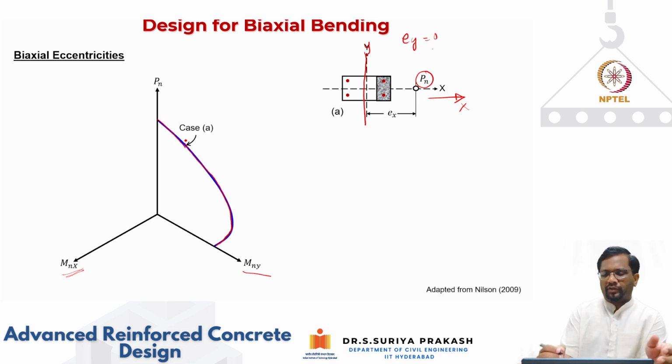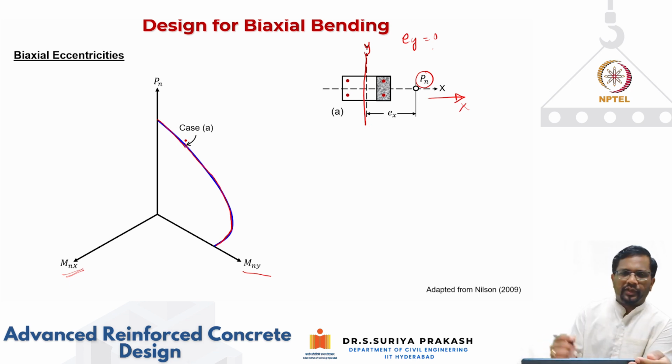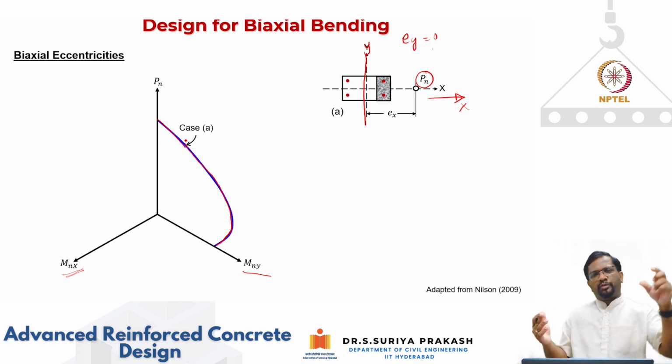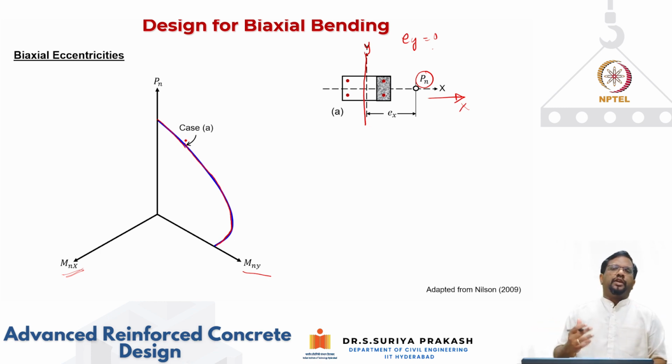Again, the neutral axis, if you look at it, we have looked at different cases. Neutral axis can be within the section. Neutral axis can also go outside the section. Depending upon the value of neutral axis, we also fix the value of your top compressive fiber strain, right? Which is basically 0.0035 minus 0.75 times epsilon c minimum. Epsilon c minimum is the compressive strain at the least compressed stage. So we derived that using similar triangles, right?